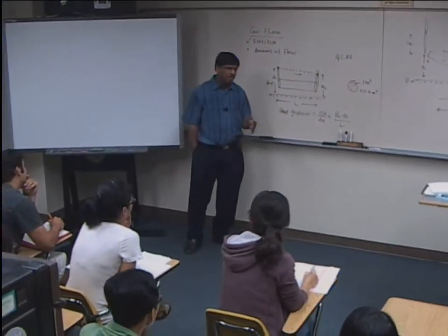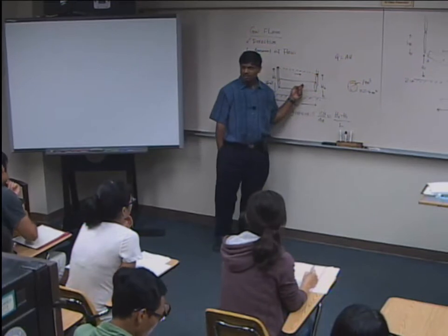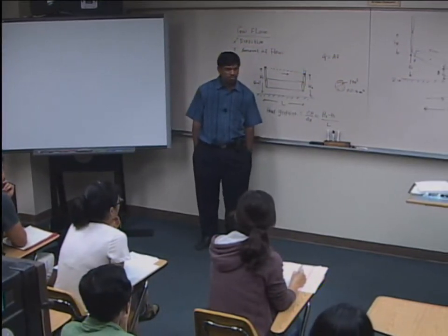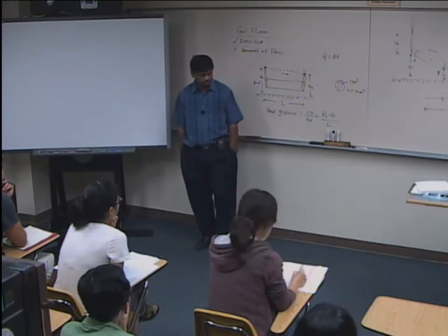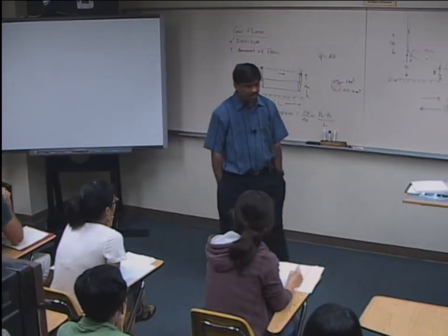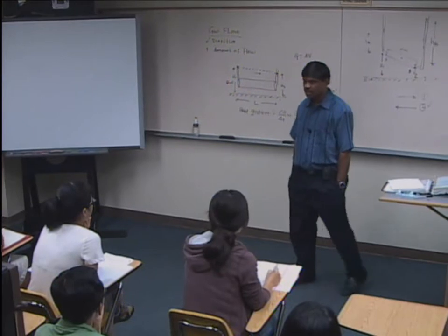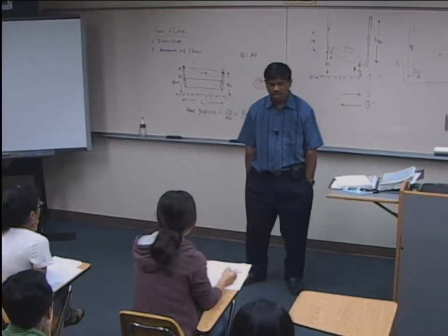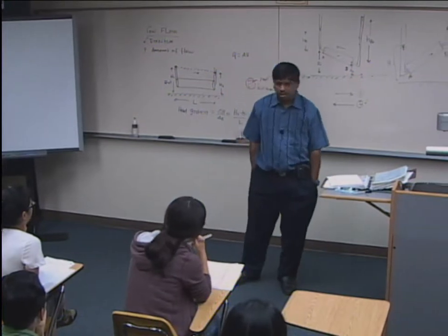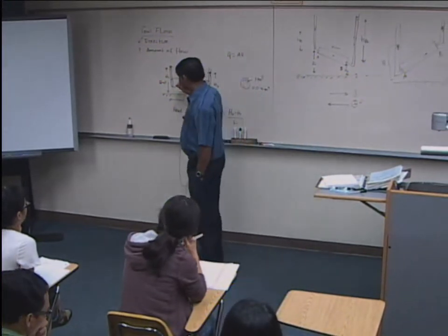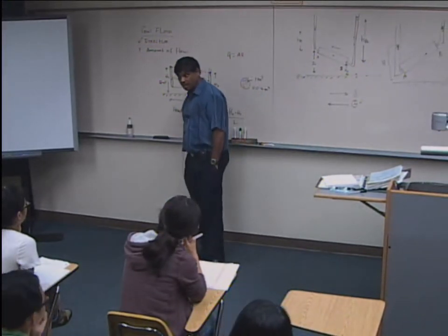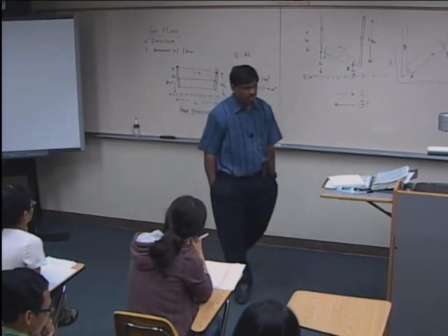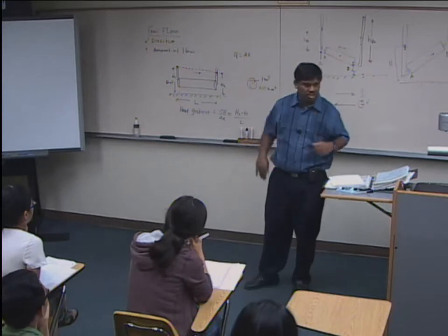Okay, let me put it the other way around. What if I fill this with sand as opposed to clay? Where do you think the water will move? More water will move. First of all, between sand and clay, is there a porosity difference? Actually, clay has got slightly higher porosity. Q will be less for clay. It's got a higher porosity. It's roughly 0.5 porosity because of its plating structure.